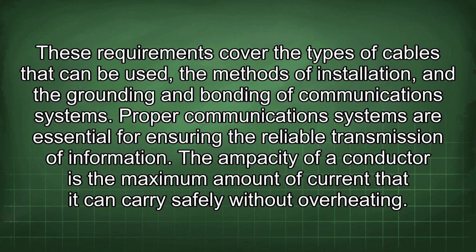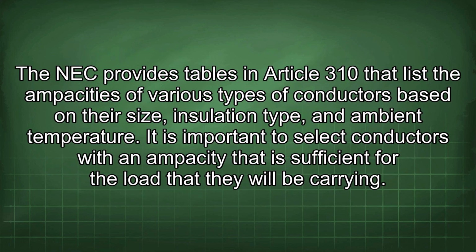The ampacity of a conductor is the maximum amount of current that it can carry safely without overheating. The NEC provides tables in Article 310 that list the ampacities of various types of conductors based on their size, insulation type, and ambient temperature. It is important to select conductors with an ampacity that is sufficient for the load that they will be carrying.